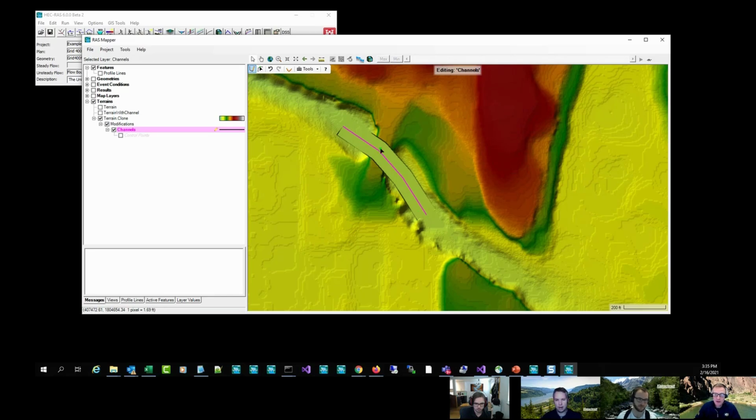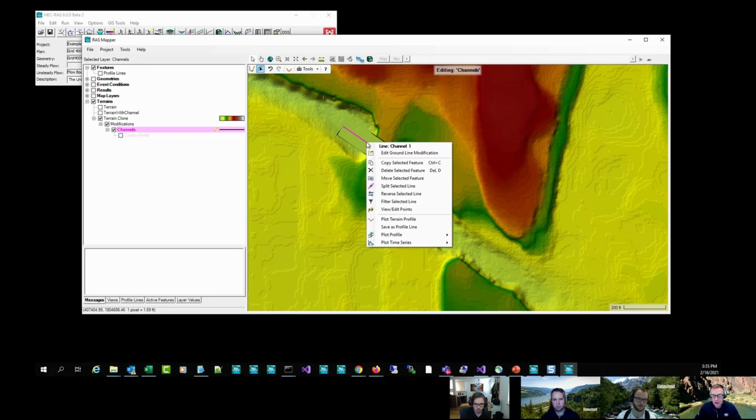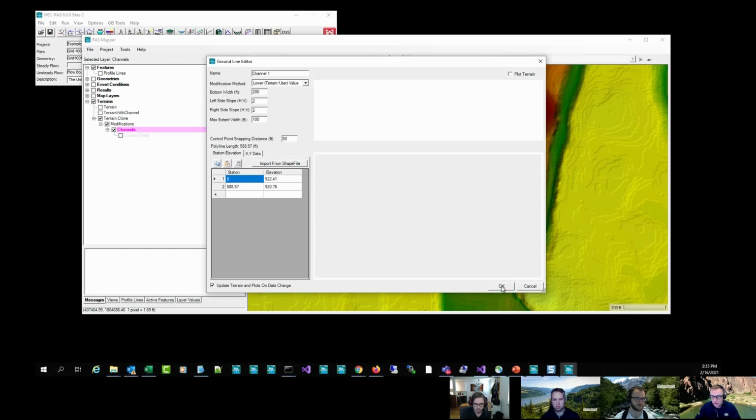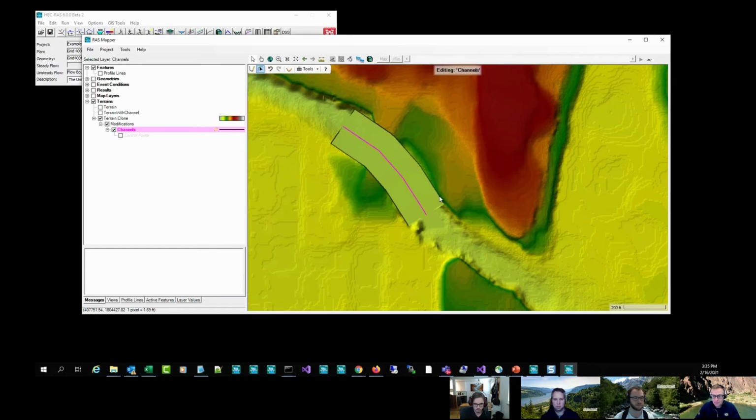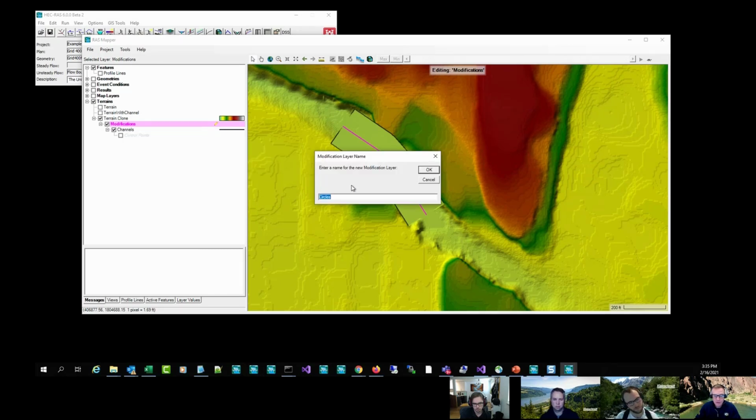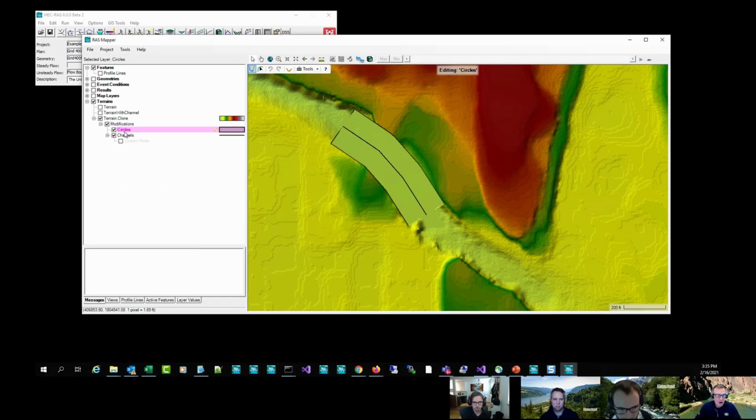Now what's the other thing we need to do? Well, actually let me modify this. This is great to show you guys. I don't like exactly what happened, so I'm going to edit it, and I'm going to make this 200. I want to really blow that channel open, because the next thing I want to do is add in some piers. So I'm going to go to modifications. I'm going to add a modification, and this time I'm going to do a simple shape. I'll just do a circle. And I can call those piers or whatever I want to call it.